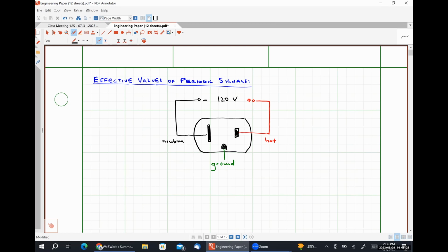What does that represent? Is that the magnitude of the AC voltage? Well, not exactly, okay? So that 120 volts is what's called an RMS voltage. And we'll talk a little bit about what RMS means here in a moment when we're deriving things. But effectively, it is a shorthand notation for the following voltage signal. V of t, a time varying voltage, which is what we would expect for an AC system, would be somewhere in the ballpark of, let me get my calculator out here to give you a more specific number.